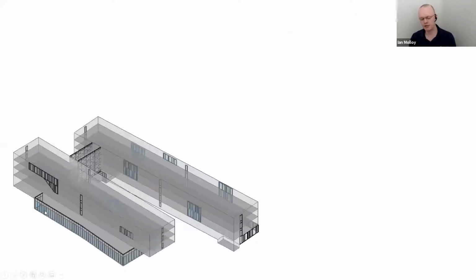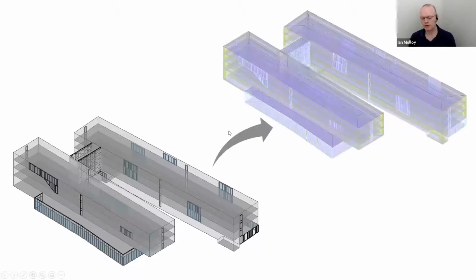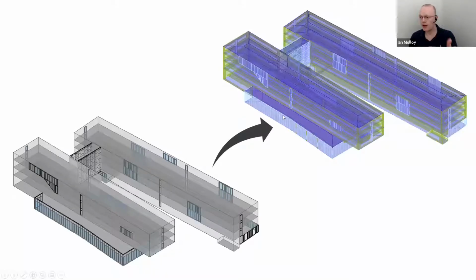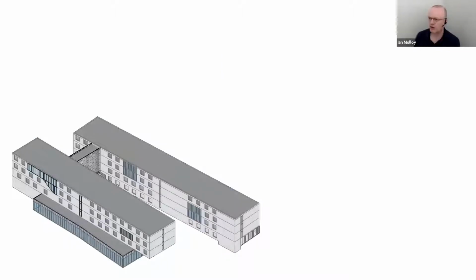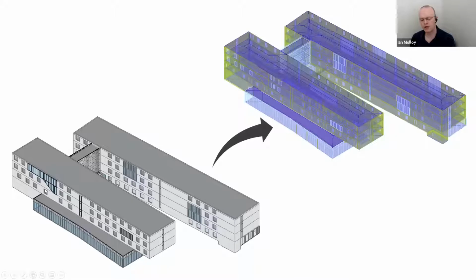Because we've now modeled a curtain system on that wall, when you create the analytical model, the curtain system overrides the original conceptual default setting. So this is a principle that happens here. And then beyond that, you can very quickly create a detailed model or detailed element model. Note, there's still no interior layout or anything in here, but we are now seeing the fact that you've got a rough window design and so on. You'll start to see the analytical model is getting more precise, more reflective of whatever it is you've modeled.